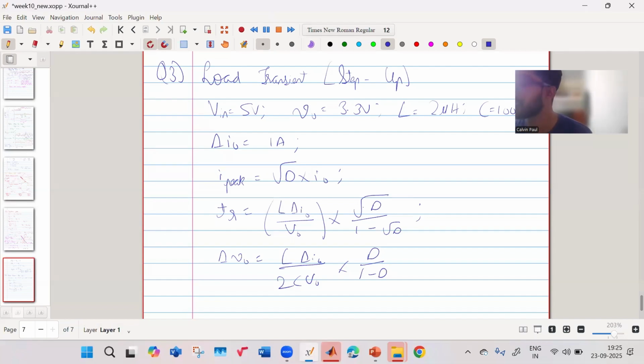So first you have to calculate your D. How will you calculate your D? What is the value of D? Vout by Vin, 3.3 by 5. Okay, so how much is that? 0.66. Okay, correct. So what is your I peak then?